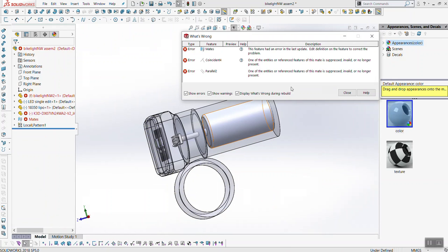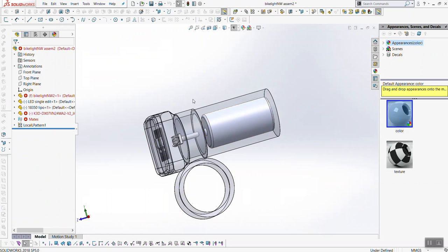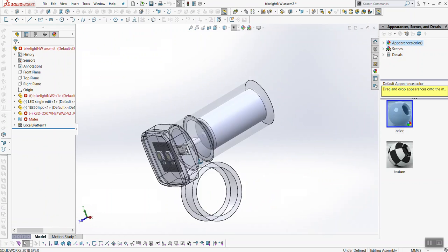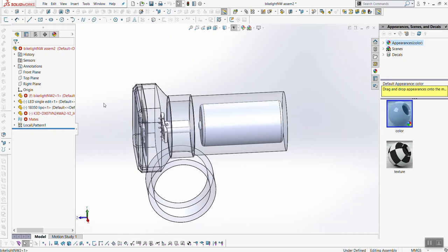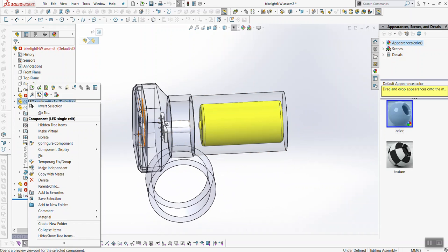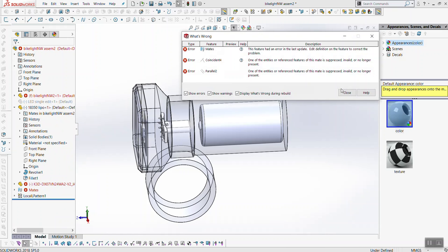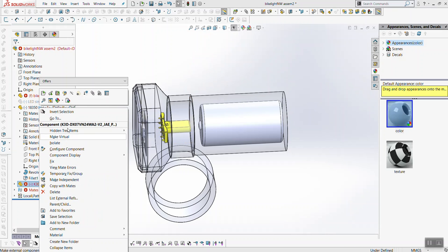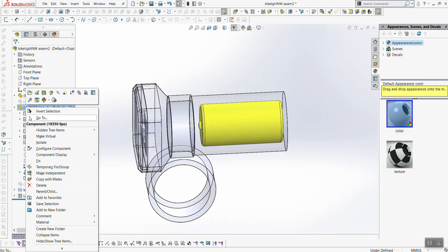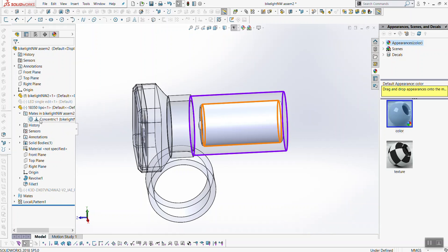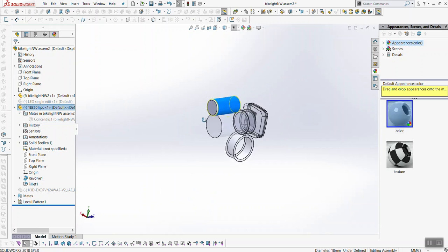The sooner that you get to this stage, the better, because you want to check your guts that you've downloaded to make sure they fit your part file. So again, in this instance, let's say I would be inserting these batteries and such. So let's imagine that I've just put this battery in here. It's giving me errors because it doesn't like that the file has been rolled back. So let's just say I suppress these mates. And now I've dropped my battery in here.